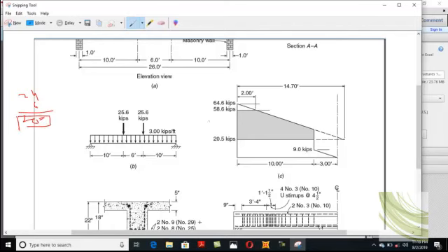effective depth. So basically here you can see that this distance is considered to be 24 inches, okay, although this distance is taken equals to d, but here they assume that this distance is equal to h, that is 24 inches means 2 foot.